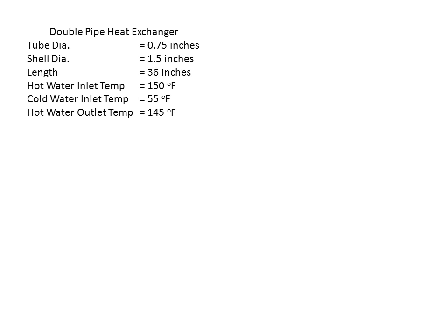Our inlet water temperature for this particular heat exchanger is 150 degrees Fahrenheit. Cold water inlet is 55, and we measured a hot water outlet temperature of 145.